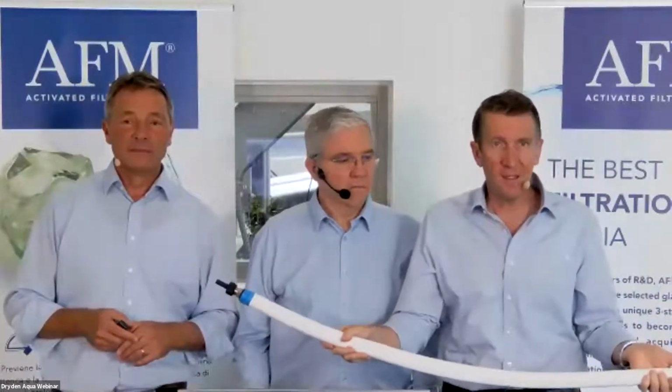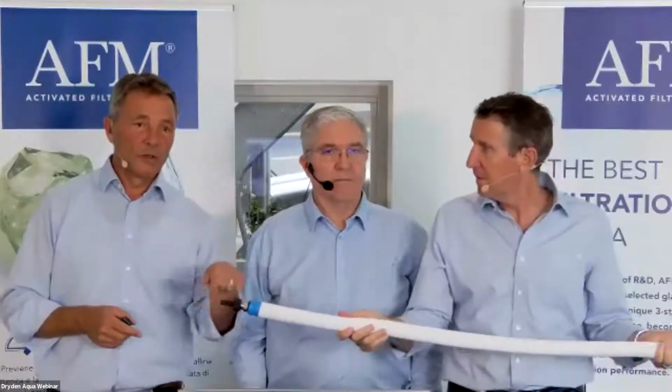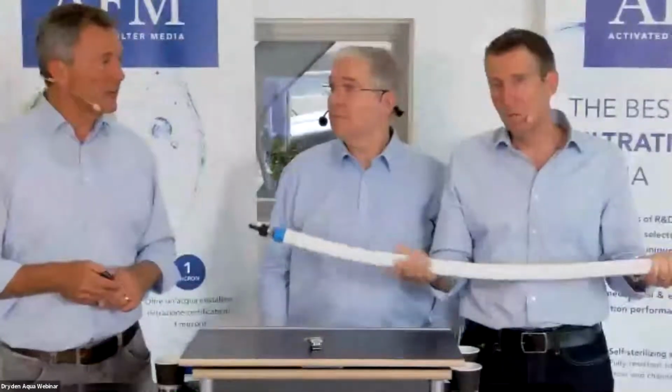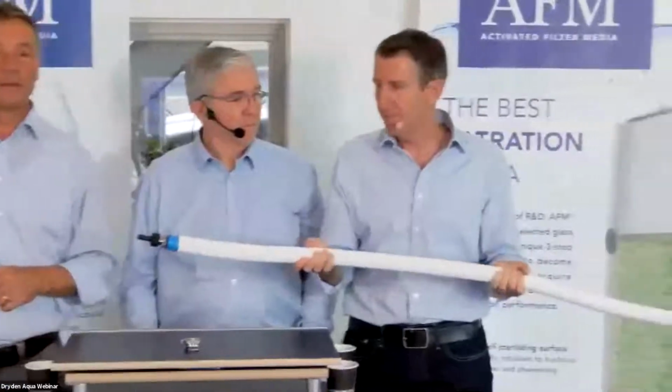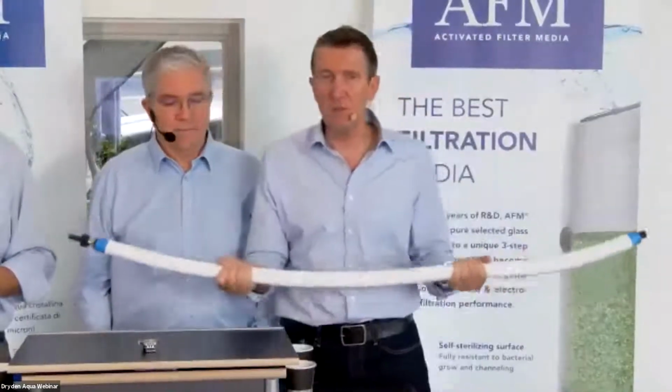So our air diffusers, they're heavy, they're ballasted, they sink to the bottom of the pit or the tank or the lagoon. They don't need to be bolted to the ground. If you're deeper than 3 meters, then maybe, or you put a weight on it. Exactly, just the weight. You don't need to bolt them down.